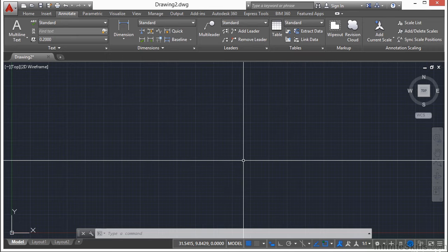We'll go over text styles and how to set them up in a different section. Now, as I stated earlier, there are different ways to use text in multi-lines, and you need to let your styles control your font type. M-text objects can be edited within the text editor, but once you do, you lose some of these controls or abilities. For example, let's load in some text, and I'll show you a trick on how to load some text.